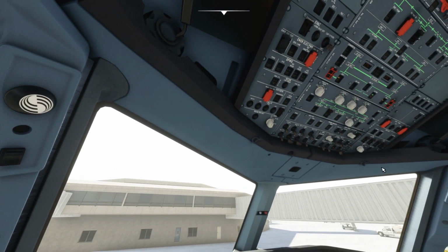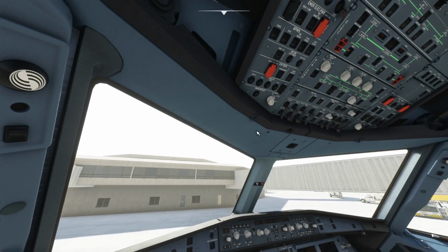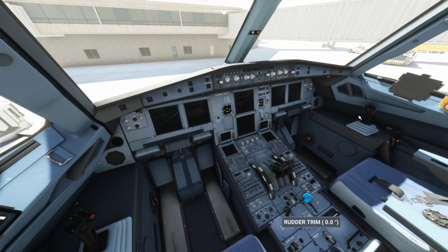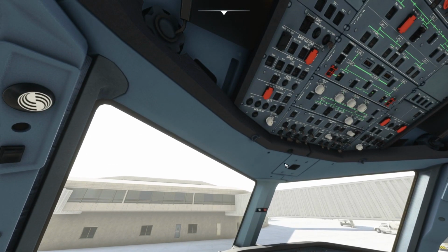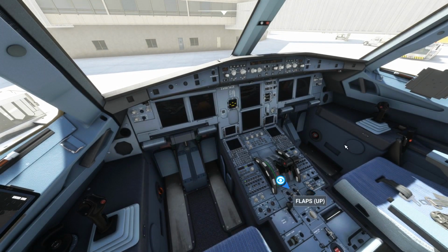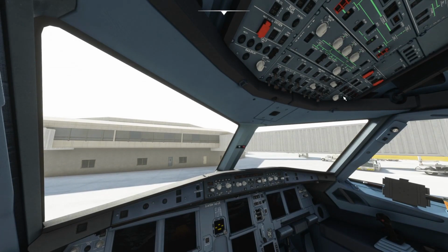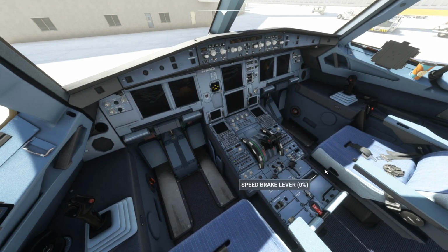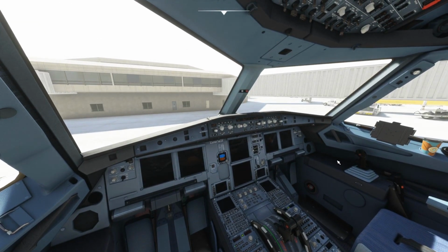Once the pushback starts, we will move on to APU, that is the auxiliary power unit. This is a generator in the plane which gives power to the plane till the time engines are on. And once the engines are on, then we will cut off the APU, and then the power will be given to the plane by the engines. So three procedures: first ground power unit, then APU, and then the engines. So three things you have to keep in your mind.